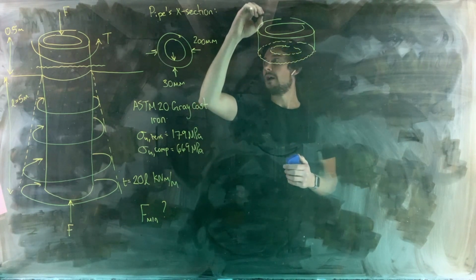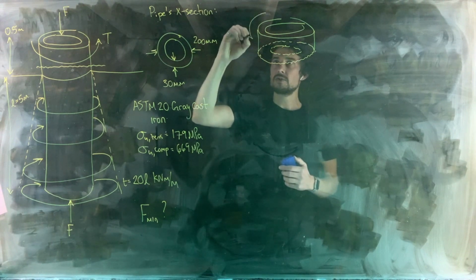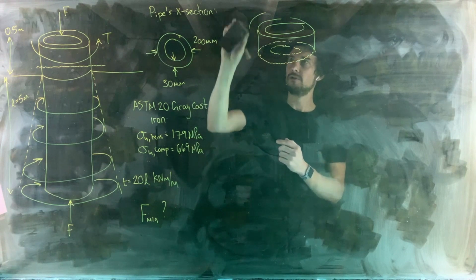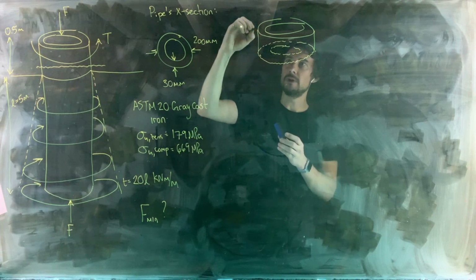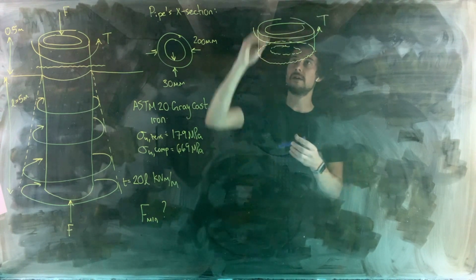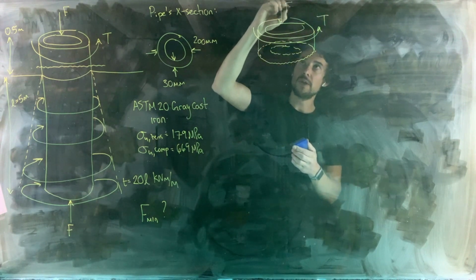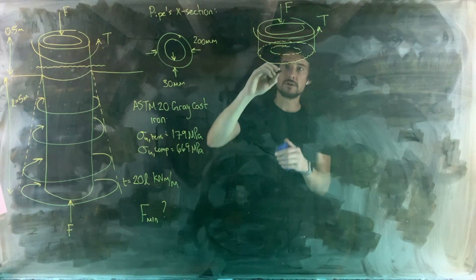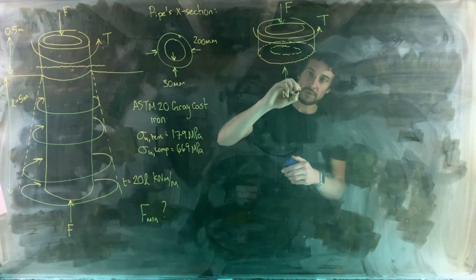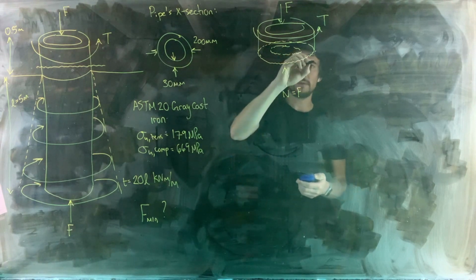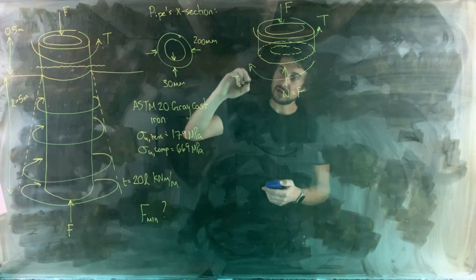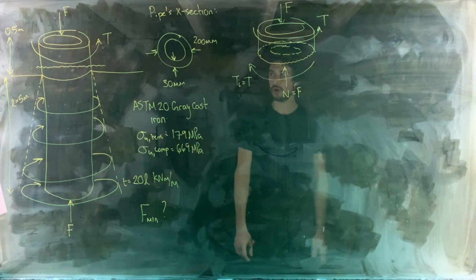Okay, so we've got our external torque that's being applied, T. Maybe that's not, I was trying not to clutter things up by drawing too many lines close to each other, but I don't like the look of that. So T there, and then we've got our load F. And what are our internal forces going to be? We're going to have an internal normal force that's equal to force F, and we're going to have an internal torque Ti that is equal to torque T.